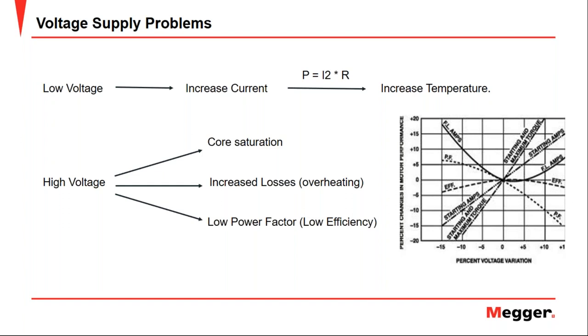There is one exception. It is when we are working with VFDs. The VFDs create their own voltage condition downstream. Whatever happens downstream of the VFD is not caused by what is happening upstream of it. Think of the VFD as creating 100% of the voltage condition downstream.